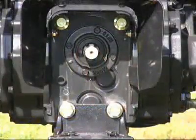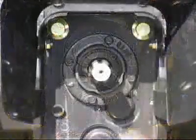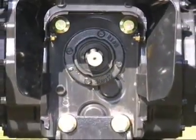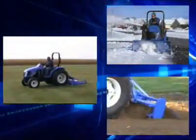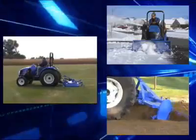Now, let's talk about the back of the tractor. The first term you should know is PTO, or Power Takeoff. A PTO is a spline shaft that is driven by the tractor engine. Every tractor has a rear PTO. Some models also offer a mid-mount PTO, located underneath the tractor. You'll use the PTO to power a huge variety of implements, like a mower, snowblower, or a rotary tiller.